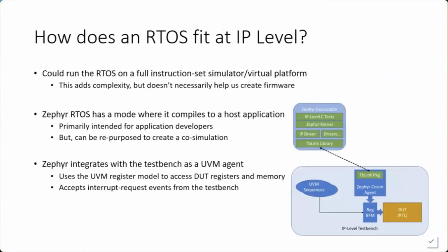So let's talk about how we might integrate a Zephyr type environment with our IP UVM verification environment. So first off, it is C code, so we can compile it, but recognize that it creates an executable, so we can't necessarily load it in via DPI. We could cross-compile this to the processor architecture that we believe we'll be targeting eventually, but this has its challenges as well, and it doesn't really bring us that much benefit.